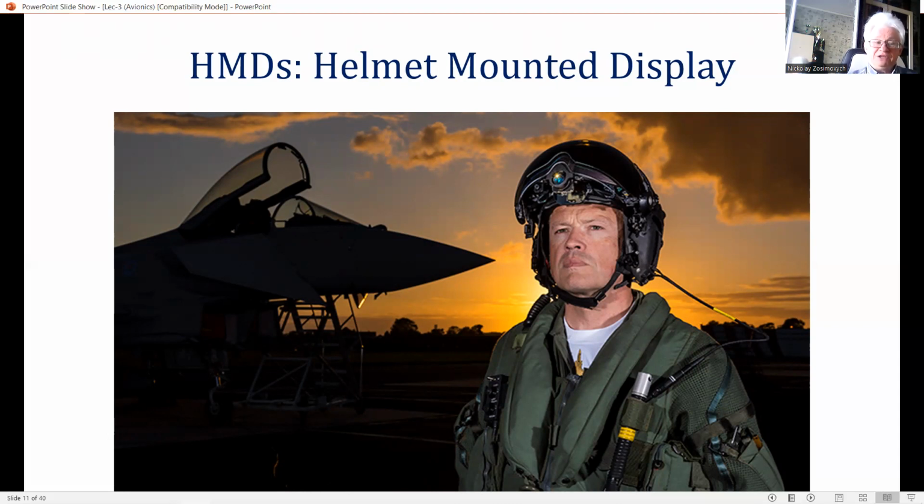The helmet must fit securely on the pilot's head and not move about, so that the display is visible under all conditions, and the pilot's LOS can be inferred from measuring the attitude of the head with the head tracker system. The HMD optical system must be rigidly fixed to the helmet with adequate mechanical adjustments to accommodate the physical variation within the normal pilot population, interocular distance, and eye relief.